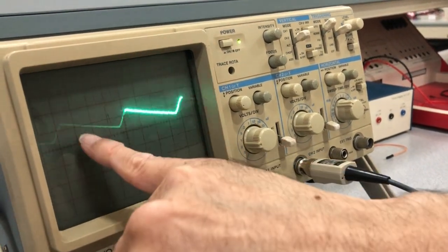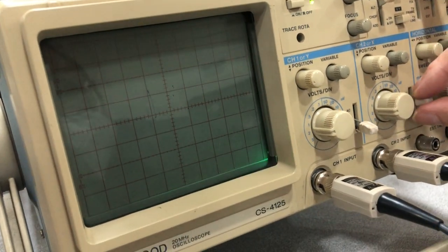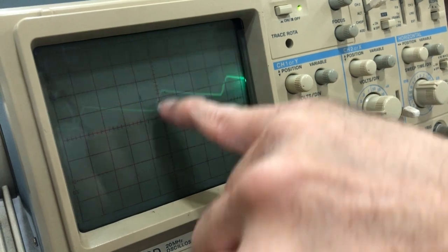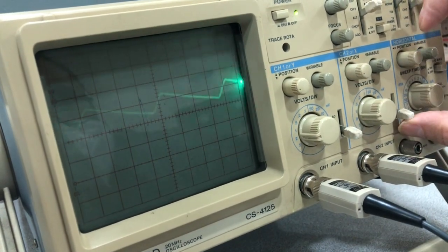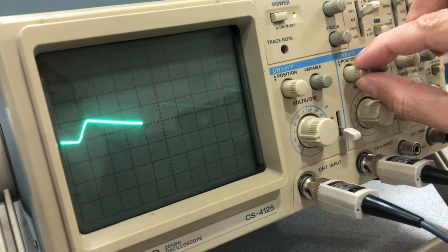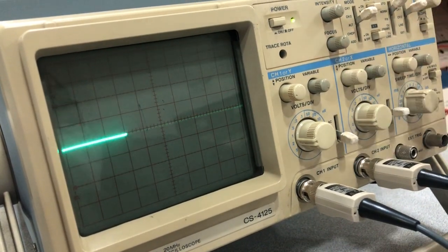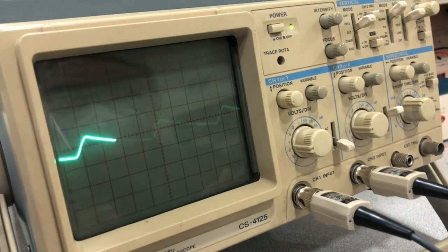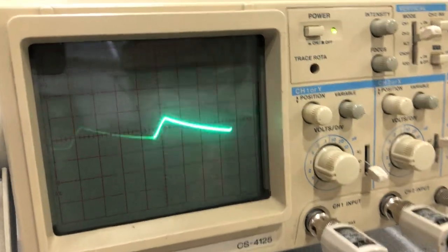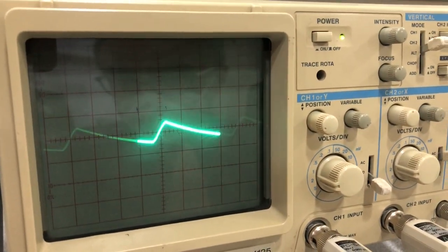The average signal with respect to zero, the zero is down here. The average DC is the horizontal line between the minimum and the maximum. I bring the zero line to the center. Okay, now go to AC. Notice DC was eliminated because we inserted internally a capacitor in series with the signal. The DC is eliminated. Only the AC passed through the capacitor.